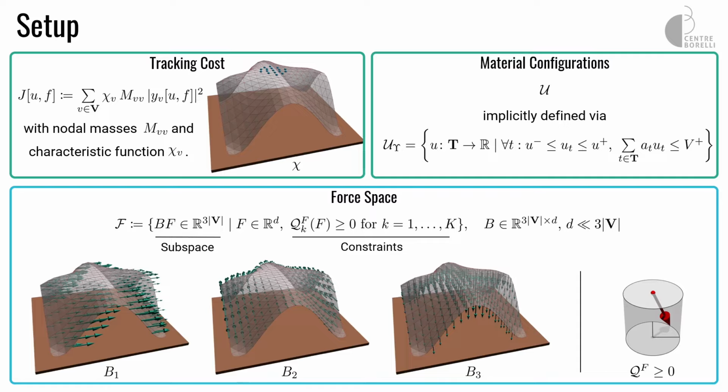Okay, so it's a cylinder because it's basically what it is. I have a constraint on the first 2 coordinates, on B1 and B2, that the norm of the sum of these 2 is constrained, right? So this is basically a circle on my first 2 coordinates, and then my third coordinate can just be up to a certain limit. They should also maybe be related, of course. If I have a lot of wind, I would have snow on my roof, given that, but it's just easier to not couple them more. This is why this is a cylinder and not a cone, for example.